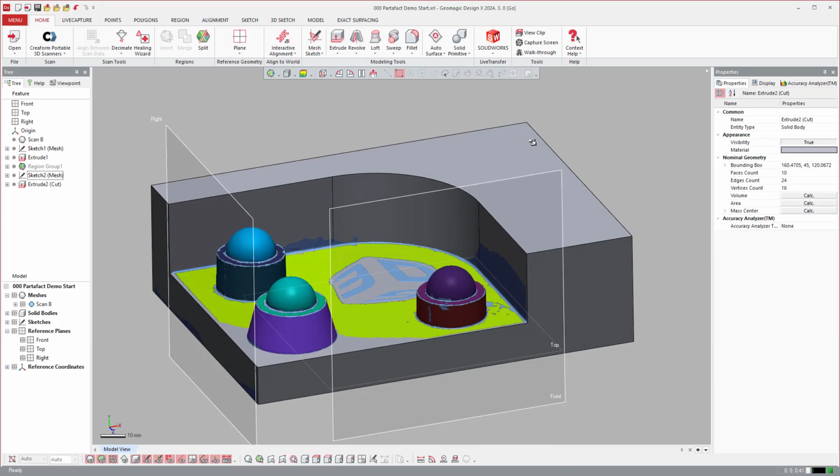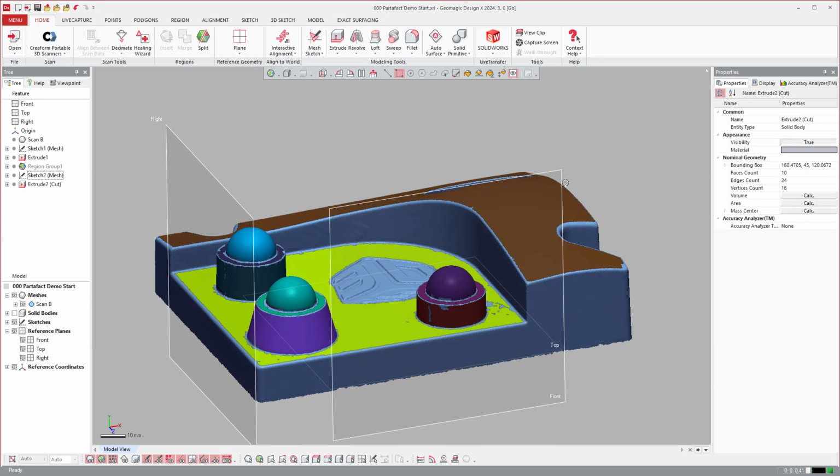Now for freeform surfaces, I have the ability to cut multiple sections through here and create a loft if I wanted to. So I could offset planes and draw profiles all the way through and create that lofted surface if you want to. Or I can also use this tool that we call Mesh Fit.